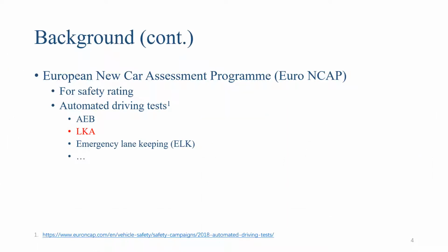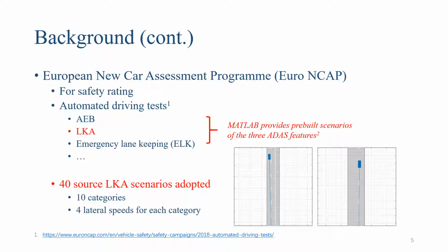We follow the European New Car Assessment Program, that is the Euro NCAP, in our experiments. It is a popular automotive safety rating system, and it has a test standard specifically for automated driving features such as AEB, LKA, and ELK, etc. And MATLAB has prebuilt scenarios of these three ADAS features so that we can directly use them to test the LKAS on the Simulink platform.